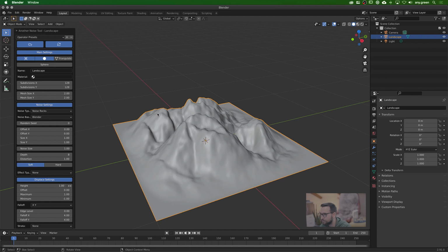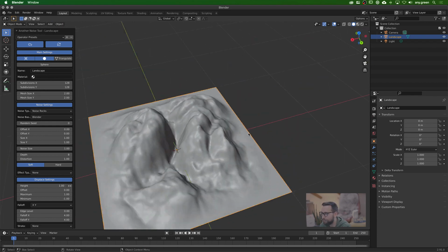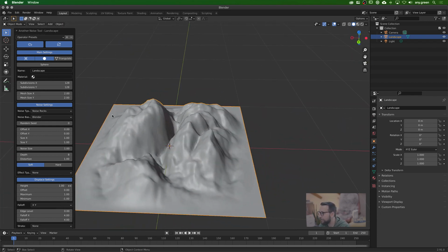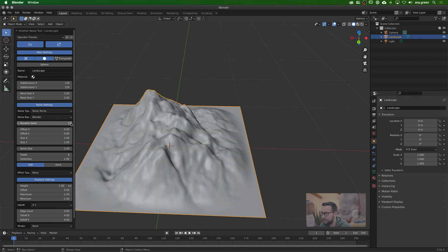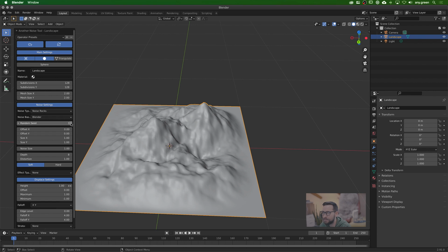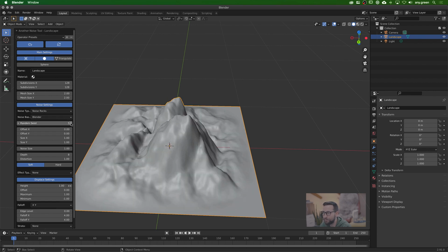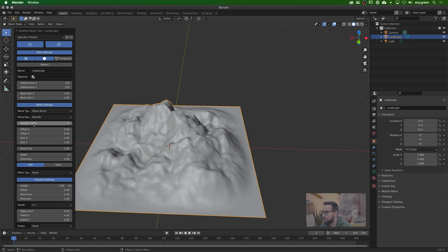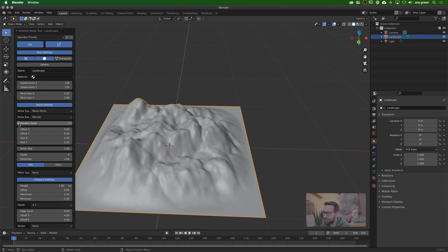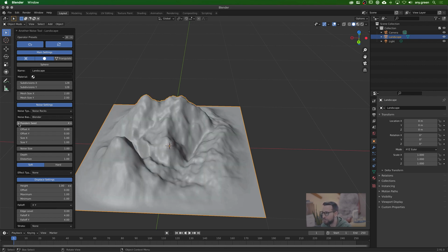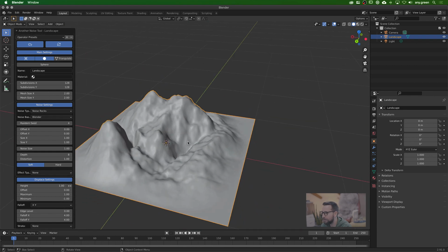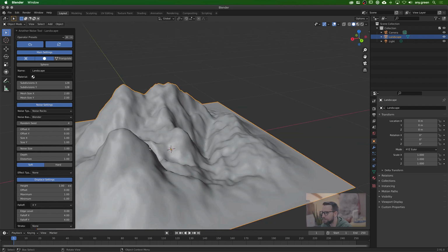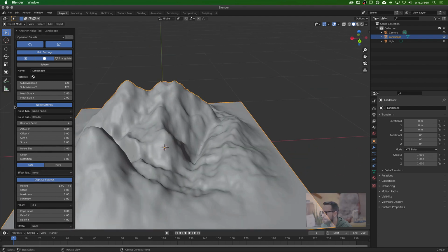Sorry. As I was recreating this, by the way, another little tip: you have the option over here to change the random seed, and by doing that, it is using the same type of noise, but it is creating very different variations. So once you have a noise that feels like it could go in the direction that you want, just play around with the seed and see if you might be able to find a different one that creates something even closer to what you were looking for.